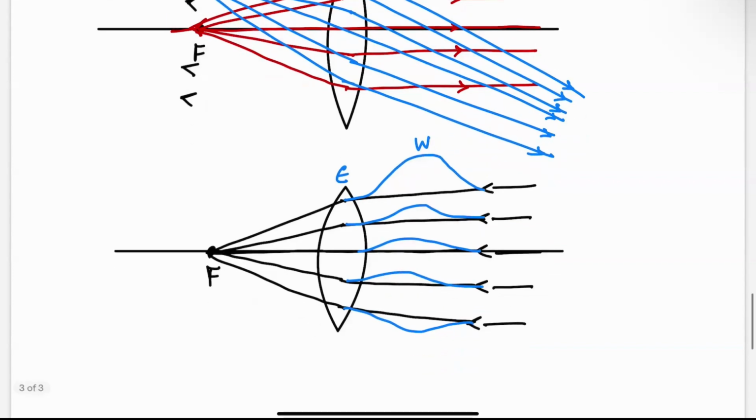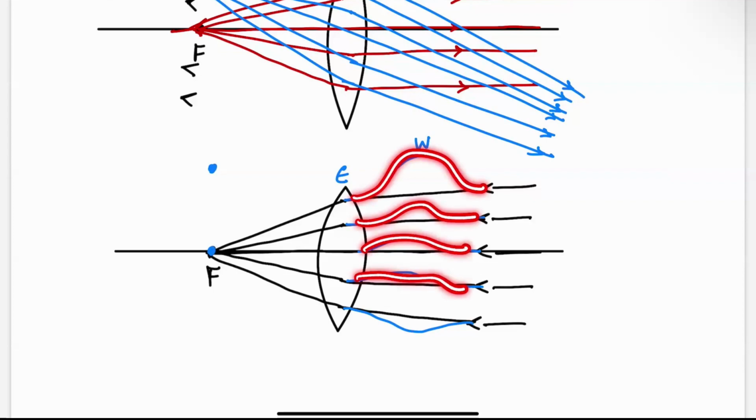Then with this extra degree of freedom, can I have a second focus such that if I have some point up here, then when I excite from here, all of these are in phase. And when I excite here, I get a phase gradient, right? So that's the idea: if I add a second degree of freedom using some extra lines here, some arbitrary lengths, then can I create a second ideal focus? So I have one ideal focus here.